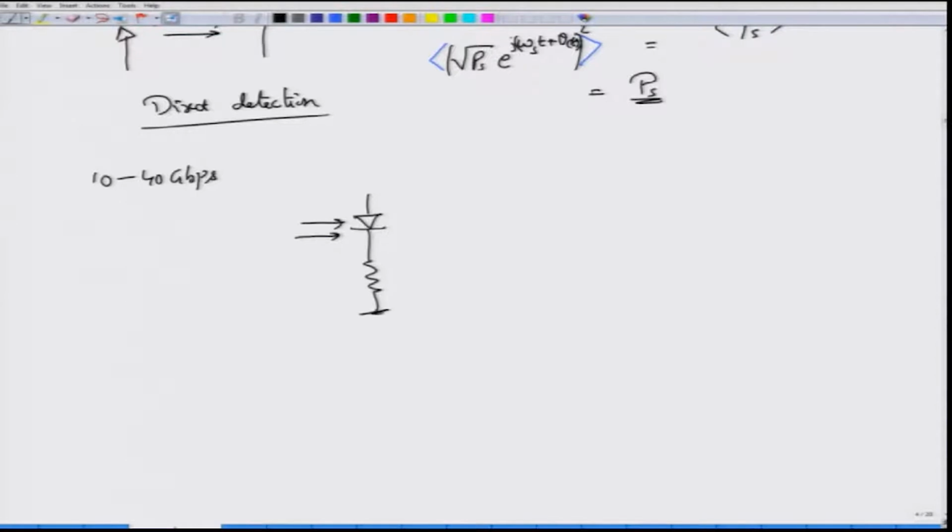Okay. This photocurrent can flow through a certain resistor generating the voltage, or in the more common scenario, you can convert this photocurrent into a voltage by putting a current to voltage converter in this fashion. This one is a simple receiver module, whereas this is called a transimpedance amplifier. Okay.